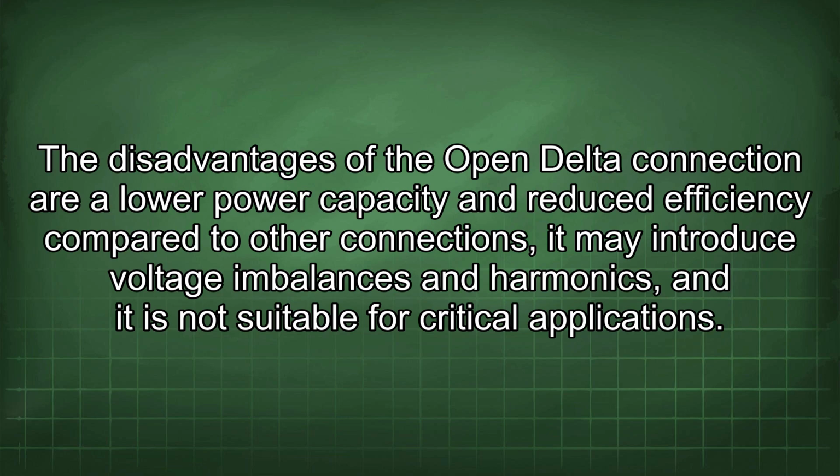The disadvantages of the open delta connection are a low power capacity and reduced efficiency compared to other connections. It may introduce voltage imbalances and harmonics, and it is not suitable for critical applications.